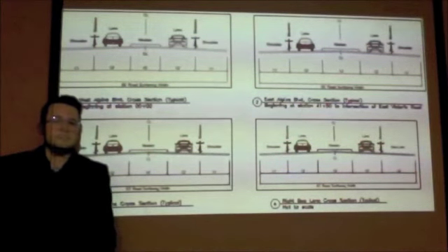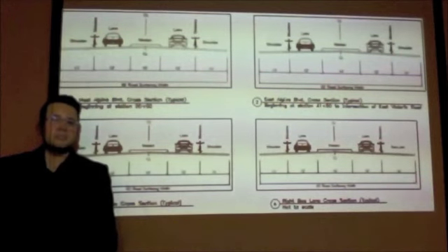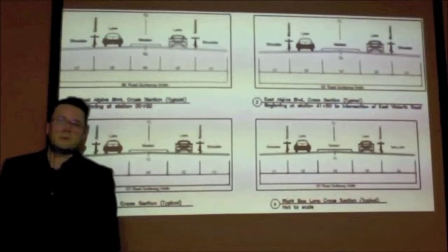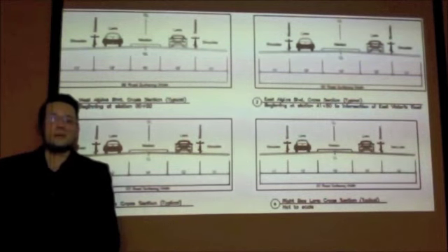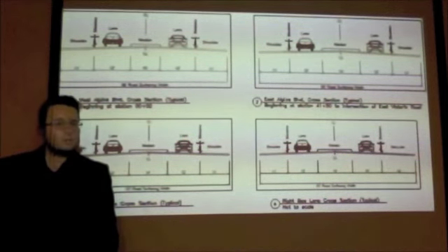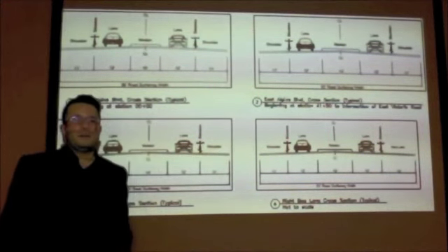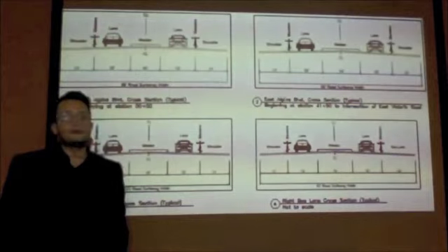This classification is a series of dimensions and specifications that are outlined in the County of San Diego Public Road Standards Manual. Based on them, the roadway had to be 12 feet wide with a shoulder of 11 feet, with a raised median of 14 feet wide, with a proposed speed of 40 miles per hour.